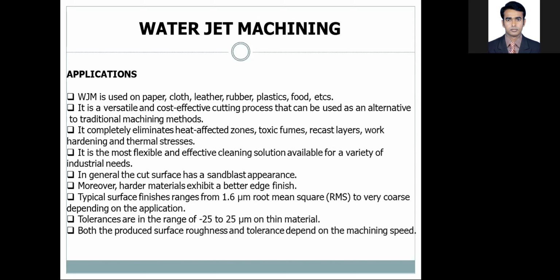Yes, you are right, Tuhin. Actually, for water jet machining, if the material is soft, for example, if you want to cut bread, then the thickness can be very high, like 5 inch or 6 inch, it can cut through. But if the material is like plastic, then the thickness will be smaller. Like plastic, polymer, thermal reinforced composite, in that case the thickness will be lower. So the thickness actually depends on the softness of the material. Okay. Any other question from audience?